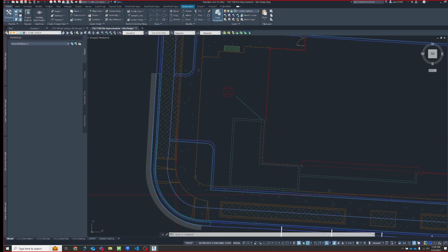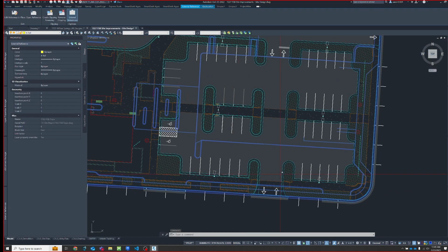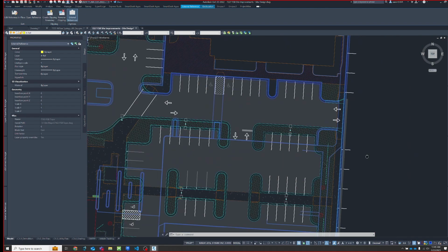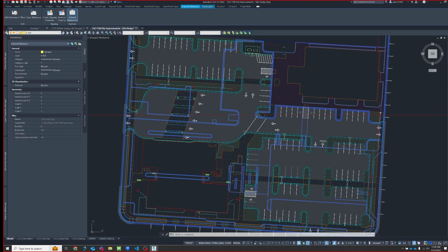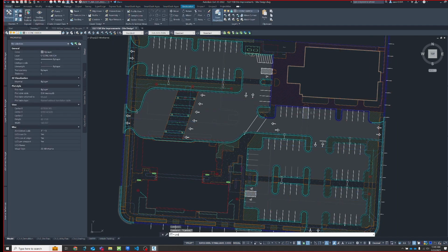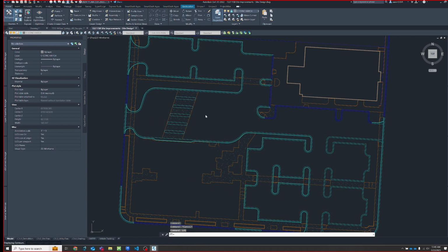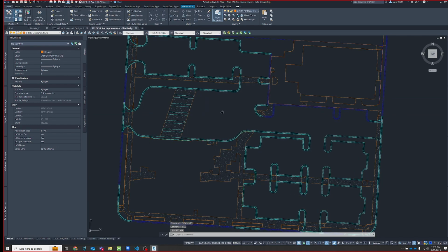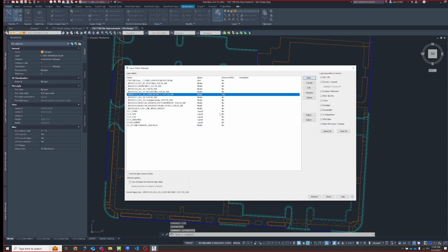So I have some existing sidewalk here. So I have everything existing selected. You can see it helped me kind of quickly, let's say, align my proposed curb all the way around this city block. The next one, it just kind of takes out a few things. And this is possibly too many of them, but sometimes I build one layer state and I quickly save another one because I only have to turn or edit a few layers on and off.